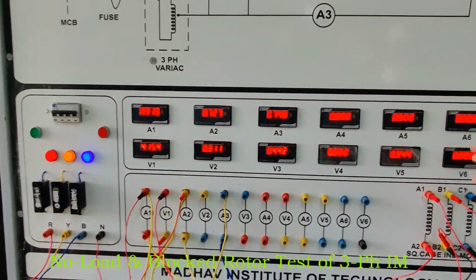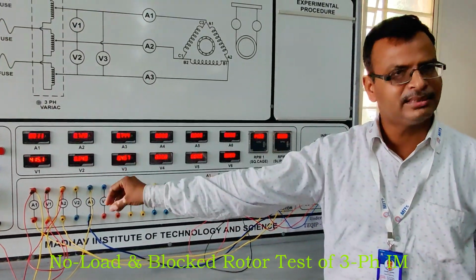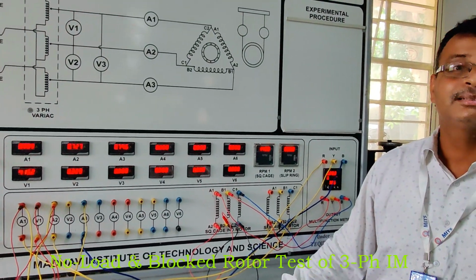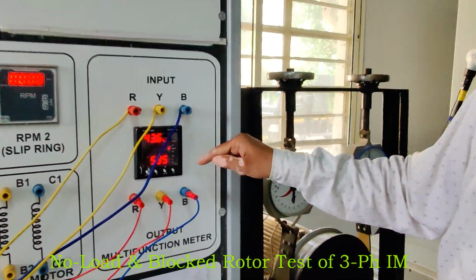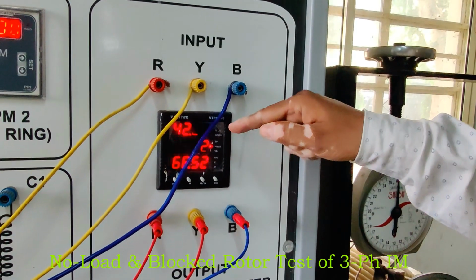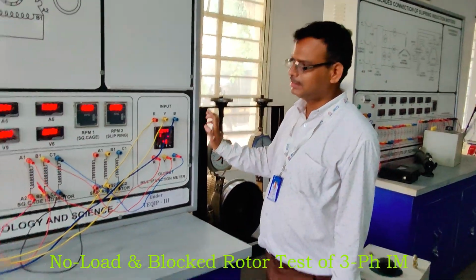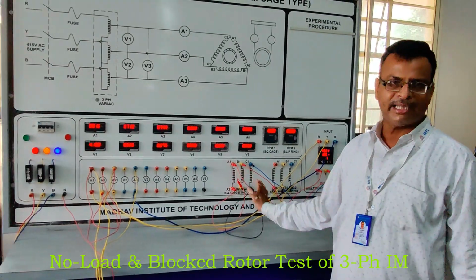With the help of these readings, you may determine the performance of this slip ring induction motor. So this is the no-load test, and this multifunction meter measures the power in each phase. 144, 19, 67, and by adding all these phase powers, you will measure the input power. So with the help of these readings, you will draw its power circle diagram. So this is the no-load test.